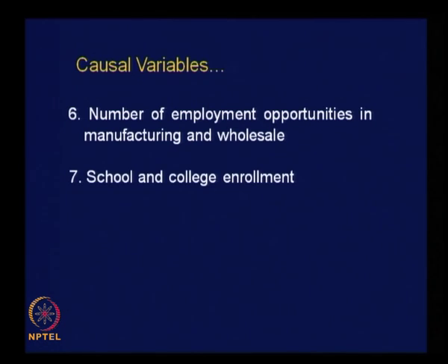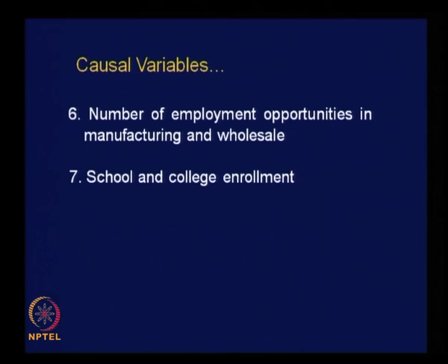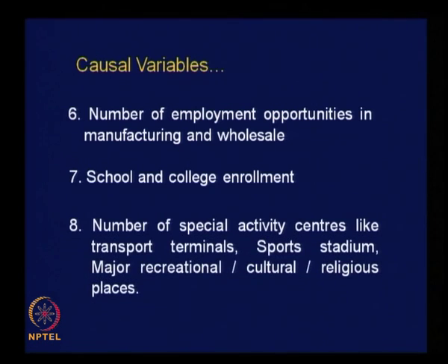In the case of educational institutions, school and college enrollment, the number of students attending a particular school or college in a particular traffic zone, will be a good indicator of its ability to attract trips. Most of the educational trips will be attracted towards that particular zone. So college or school enrollment could be a very important factor, and in addition to the zonal characteristics, there could be some special factors like this.